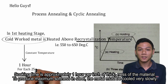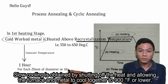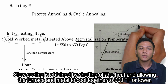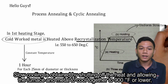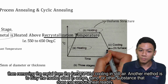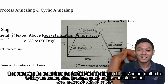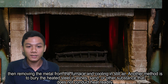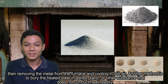To produce the maximum softness of the steel, the metal must be cooled very slowly. Slow cooling is obtained by shutting off the heat and allowing the furnace and the metal to cool down together to 900 degrees Fahrenheit or lower. Then removing the metal from the furnace and cooling it in still air. Another method is to bury the heated material or steel in ashes, sand, or other substances that do not conduct